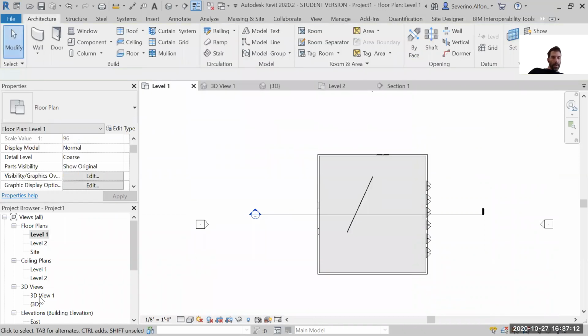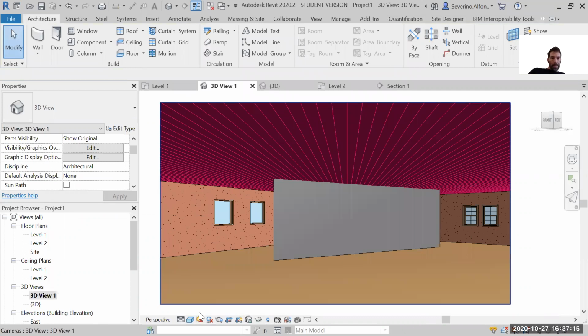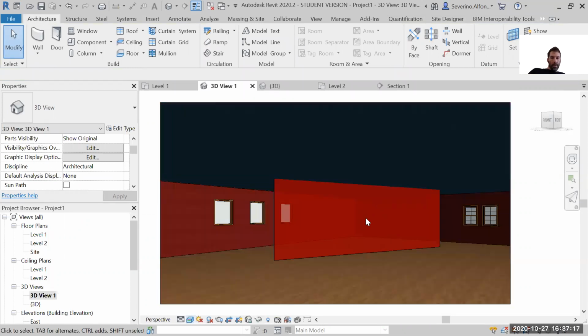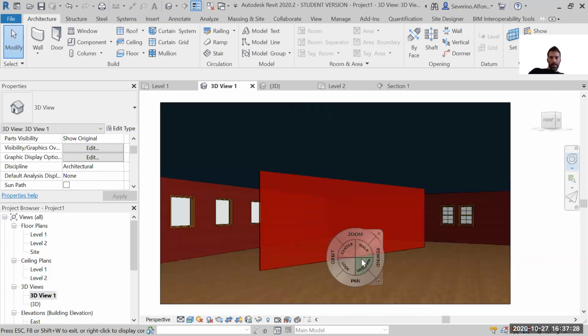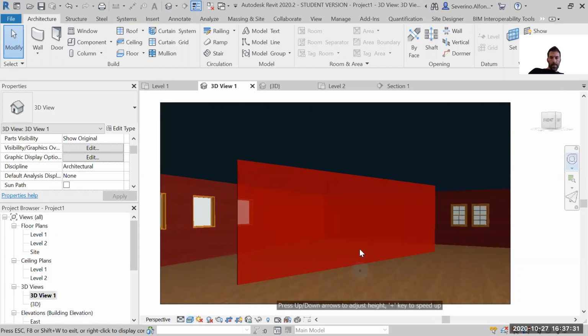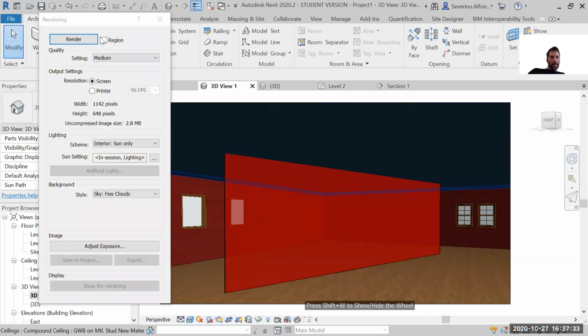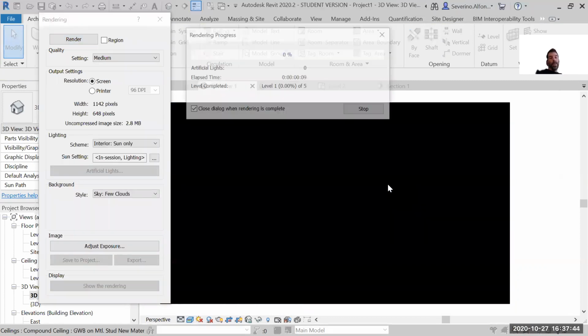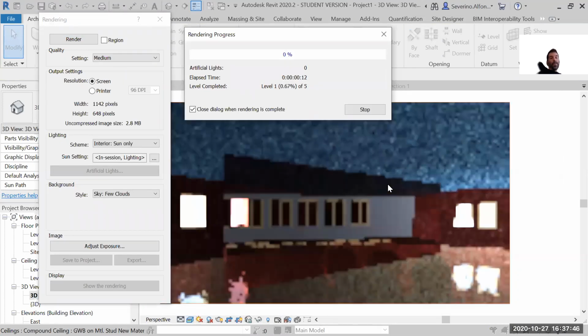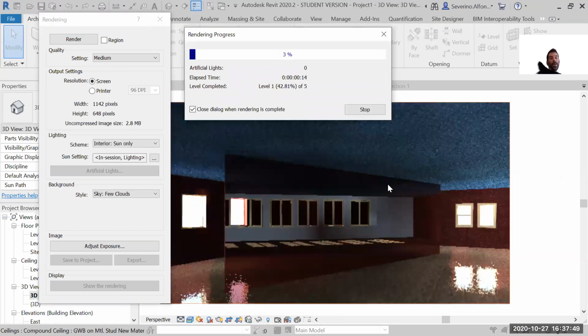And then if I go to the camera, I can make sure it's working here, background realistic, and there you have it. And if I render this, there you have a glass material that I brought from the asset browser. You can do that with all of those materials, and you have literally thousands of materials there you can choose from.